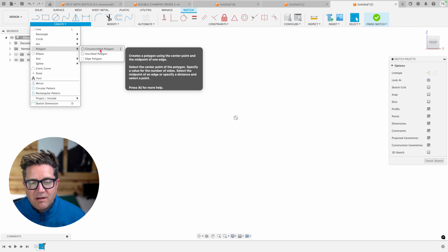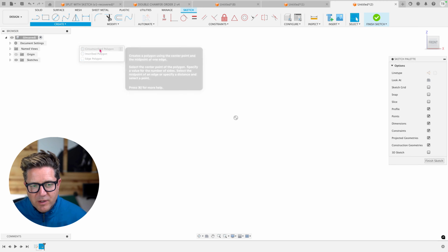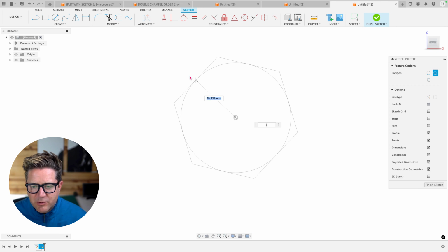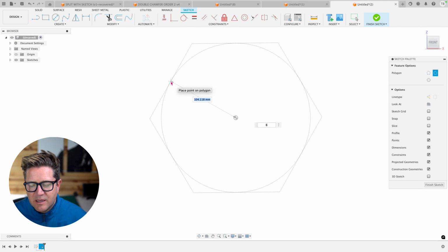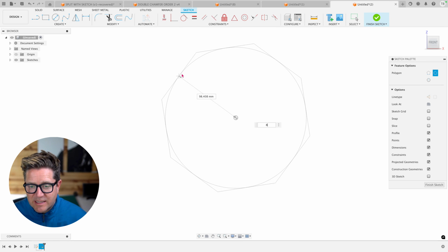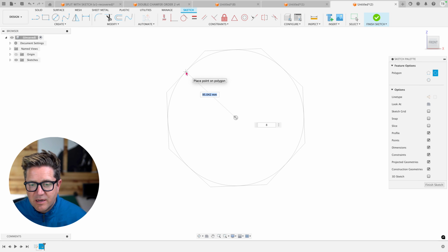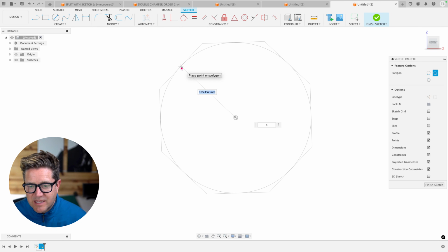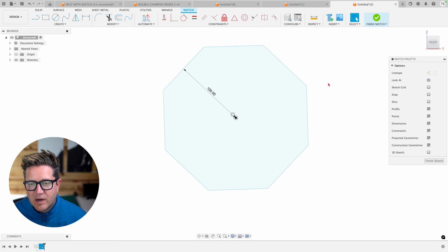If you want to create the top of a hex bolt or any other polygon, go to Polygon, and then there's these 3 options on how you place it. This one is letting you effectively place a circle in space, and you'll have an inscribed polygon. You see that 6 there? If you put in an 8, it's going to change to 8-sided, making an octagon. If I go to this value, this is that radius value of 100. Click that, and now we've got it placed.